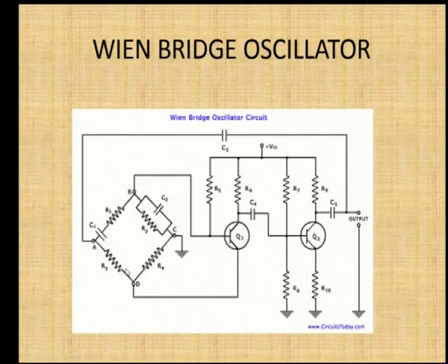So, here this is the bridge circuit, it is implemented with the same. These 2 arms A, D and C, D have only pure resistances R3 and R4, and A, B is the arm which consists of the series combination of the resistor R1, C1, and this B and C arm consists of the parallel combination of C2 and R2.